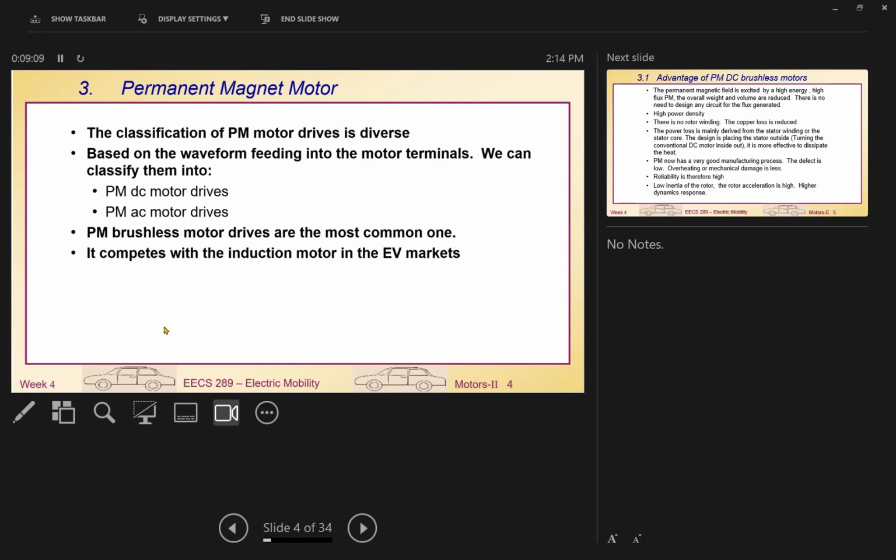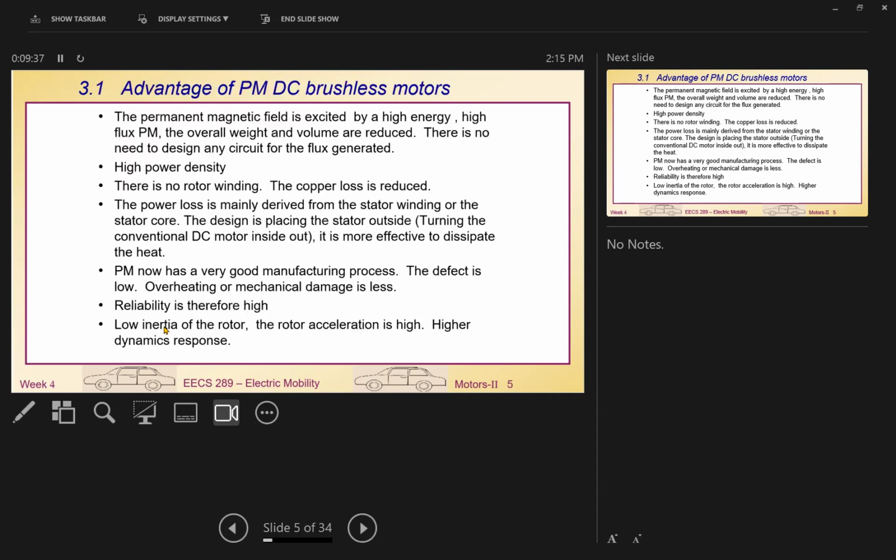Only for some really dedicated equipment, like your microprocessor cooling system, where they want really high performance, high speed. That's why they use PM. PM brushless can have high RPM, high speed of rotation, more than 10,000, no problem. So that's why they tend to use the PM. But for heavy duty, it is probably still too expensive. But anyway, that's the PM story.